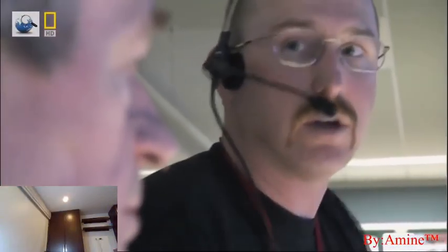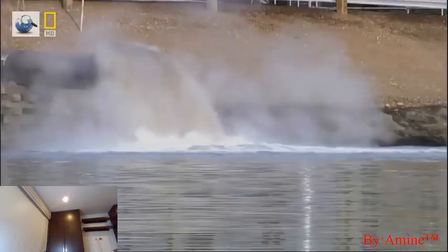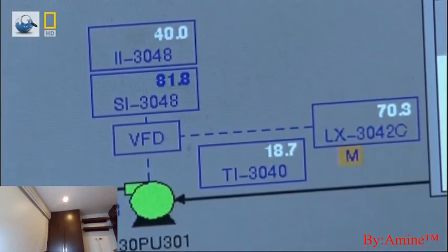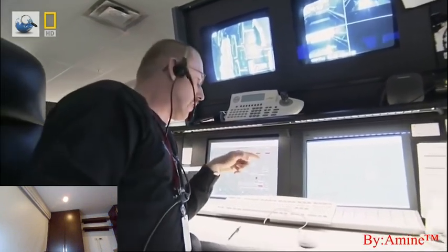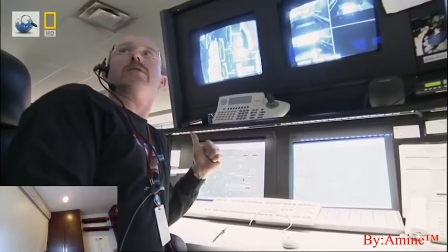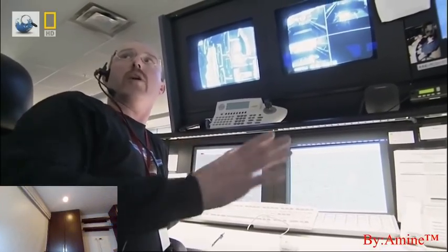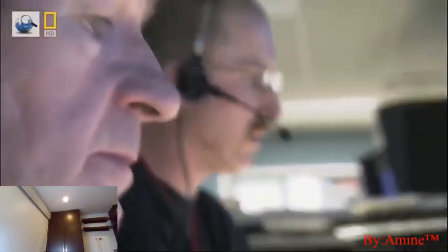His greatest worry is the integrity of the tailings pipe, which carries waste out of the operation. A clog here would be devastating. We're looking for problems with pump box levels, making sure that all the pumps are operating as they should, and that we don't lose the velocity on our coarse tails line. Our tailings line is one of our lifelines to our plant. If we lose the tailings line, we have to shut down that train. That train has to go down. We'll wait.